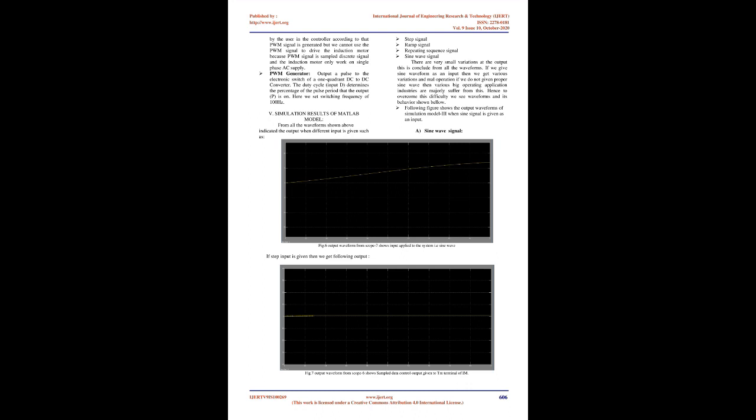PWM IGBT Inverter: here we are using a PWM IGBT inverter with a snubber resistance of 5000 ohms, built using power electronics devices like IGBT/diodes. It is used to convert DC current/voltage into AC current/voltage. Single phase induction motor: an induction motor is also called an asynchronous motor. Here we are using a single-phase induction motor of 110 VRMS, 60 Hz frequency and nominal power of 0.25*746 VA. We are using the induction motor as a nonlinear load.